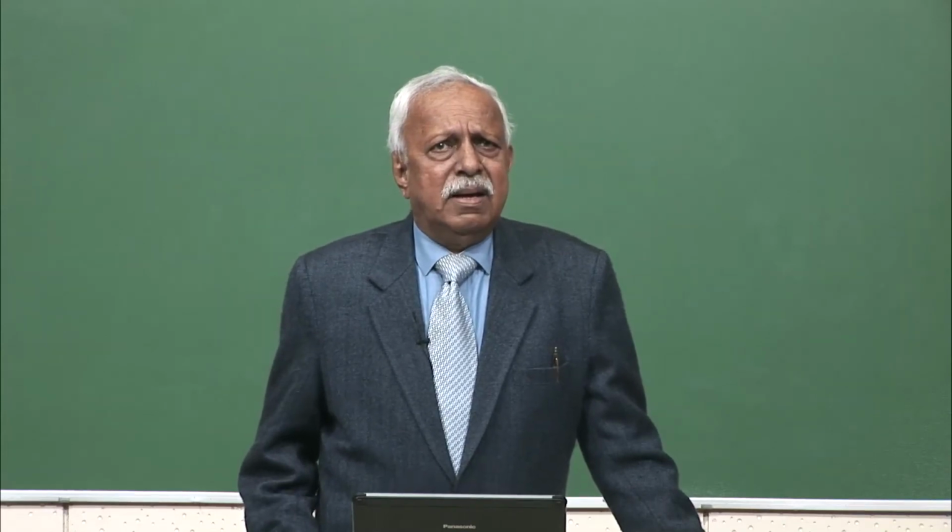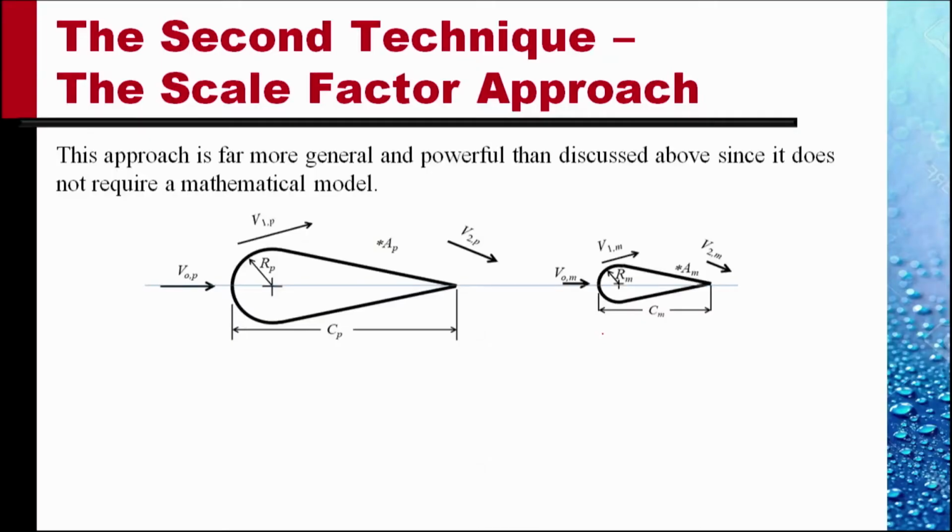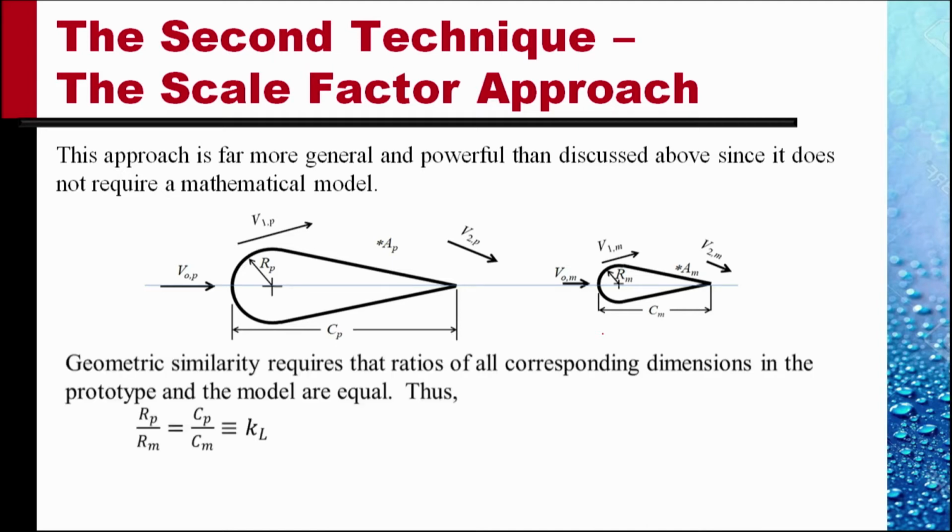Consider a model and a prototype which are geometrically similar. If the bodies are geometrically similar, this means that the ratios of all corresponding dimensions in the prototype and the model are equal.